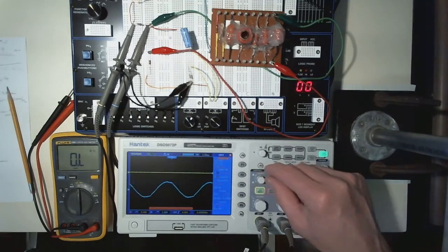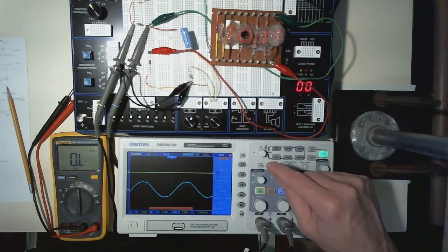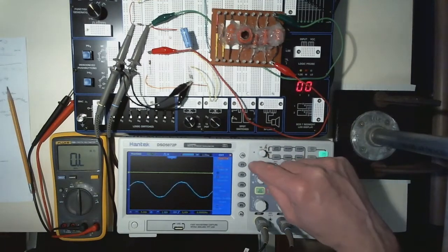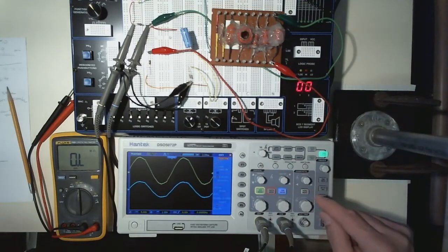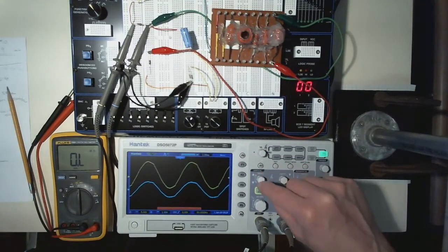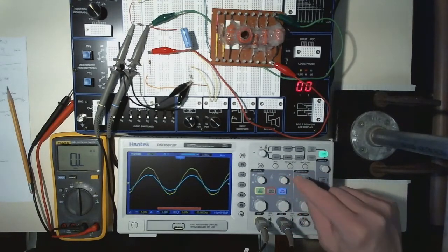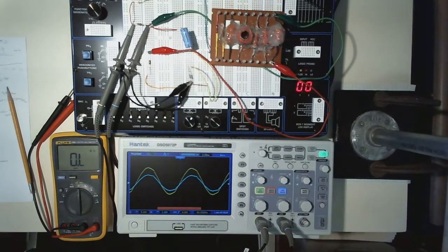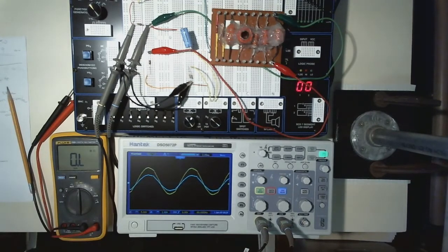Well, this is kind of a neat scope. I don't know that it's a particularly reliable scope, but it's got a lot of features on it. So I'm going to turn this back to AC and get rid of the menu. These buttons, where you move it up and down, if you just press on them, it will automatically put it at 0 for you. Let's do that. Okay, so now I have those zeroed and I can start to trust that.